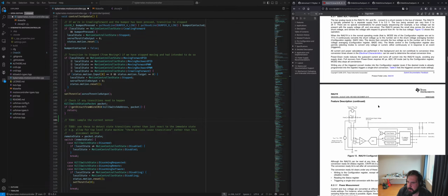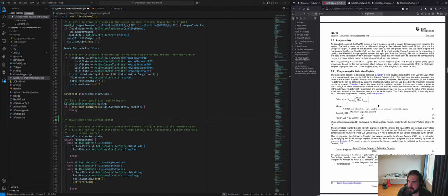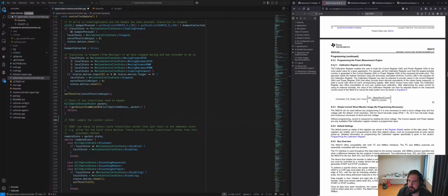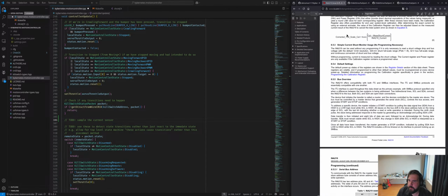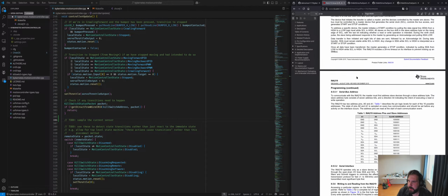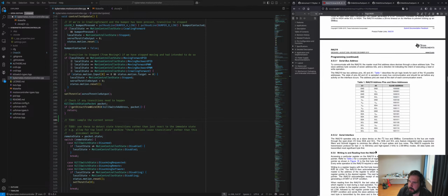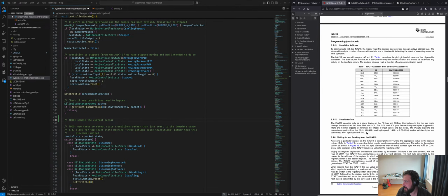All right, there's a lot of math in here that we'll have to get through, but let's start with the INA219 address and slave address pins. You can do some wacky configurations here. I connected both A0 and A1 to ground, so we're going to have this base hex 80 address up here. The INA supports the fast or high-speed modes. It supports really high-speed I2C, but the Arduino doesn't, so we're going to be using 400 kilohertz I2C on this whole thing.